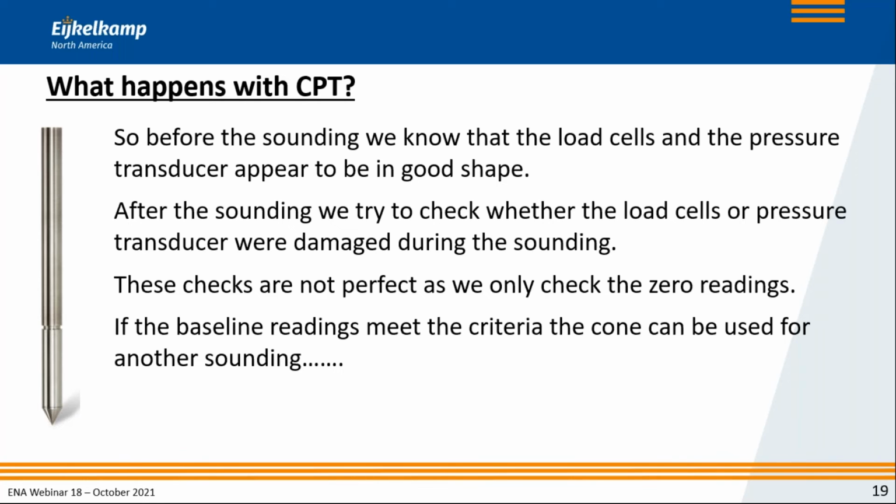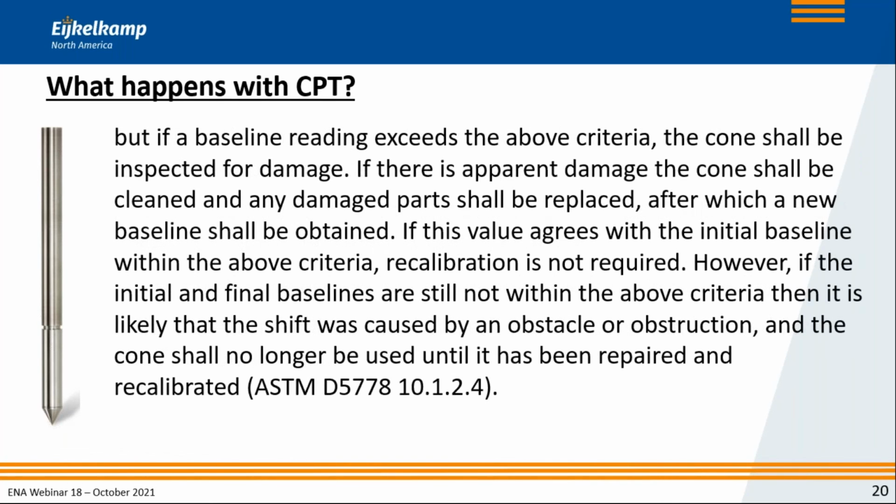before and after. And if we find out that the baseline readings do not meet the requirements, in that case, we feel that you need to start doing something. And now, because we're talking about 10.1.2.4, what you see is that if the baseline readings exceed those criteria, in other words, if we don't meet those tight criteria that we have, the cone shall be inspected.